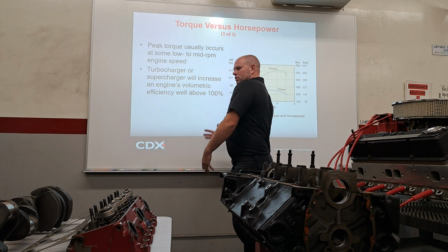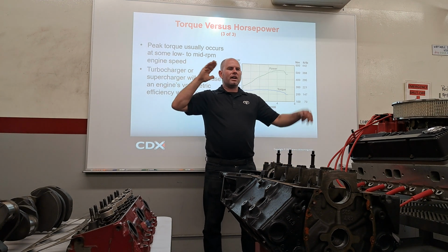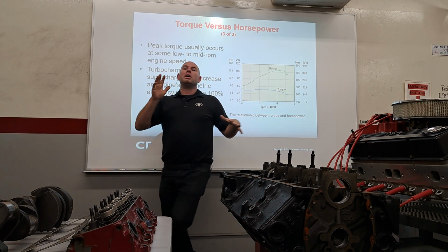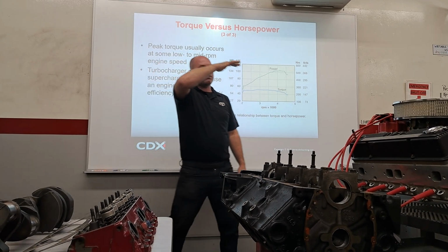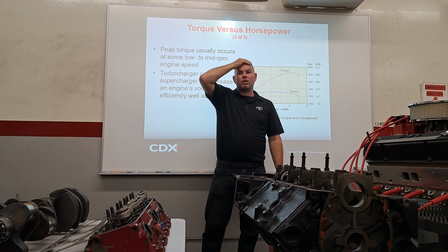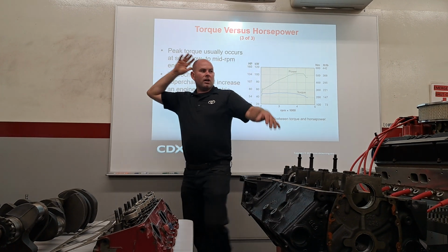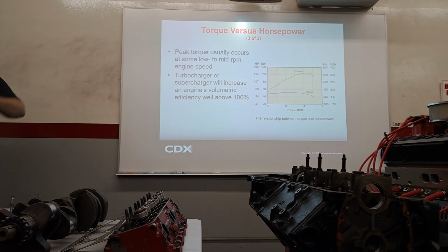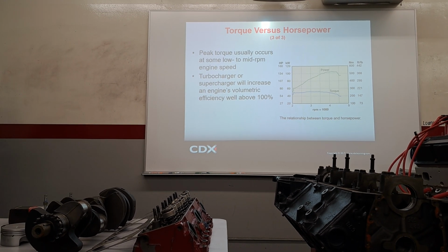Then they get into all sorts of crazy stuff. Like when you breathe the exhaust out, they'll actually start overlapping the valves so that the exhaust leaving will kind of pull the intake in a little bit, scavenging. And you can go full-on mad scientist crazy to really understand all that type of stuff. So from a hypothetical standpoint, we can't reach 100% volumetric efficiency, except Russ can, because he's the man.